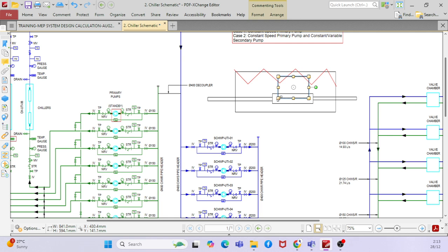This is same like say for example you have a DX system. In the DX, you have an evaporator and you have a condenser. Say for example you have a DX unit, you have an indoor unit, right? The indoor unit you can call as an evaporator, and the outdoor unit you can call as a condenser. This is your evaporator which is inside, and this is the condenser which is outside. So this condenser basically rejects the heat, and this evaporator basically absorbs the heat.